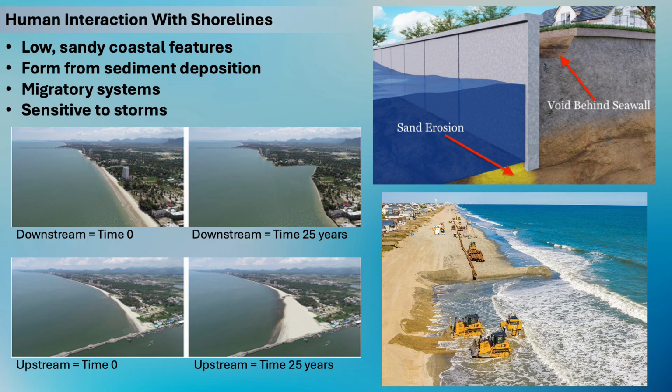Beach renourishment attempts to restore sediment balance by adding sand artificially, but without addressing underlying transport dynamics. So erosion continues. Many of our current engineered solutions do not account for wave energy and sediment transport mechanisms. All we're doing is relocating sand after erosion and placing it back in the same spots where it will erode again.